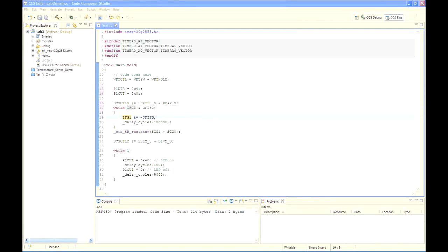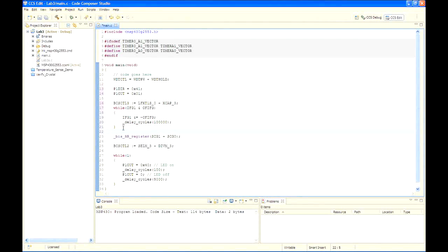So in step 19, finally we need to add a line of code to turn off the red LED, indicating that the fault test has been passed. So add this new line after the while loop: P1OUT = 0.